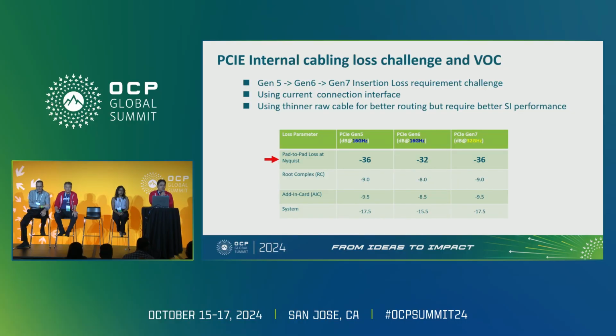However, the thicker cable is also more stiff and not easy to bend. So some customers start to look for a tiny, small cable, not from 30 to 29, 28. Instead of that, they will look for 32 or 34 wire gauge. So the thinner cable will provide much easier cable routing, more flexibility for this kind of orientation.